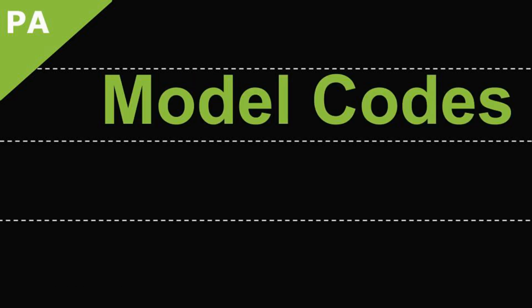Model building codes. Model building codes also use industry standards developed by trade associations. For example, the IBC references standards writing organizations such as ASTM International and NFPA, as well as standards approving groups such as ANSI. Standards are adopted into the building code by reference name, number, and date of latest revision.